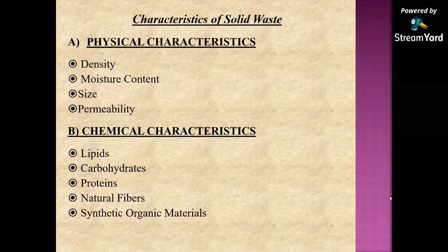Some changes in the density occur as waste moves from sources to the disposal site as a result of handling, wetting, scavenging and drying by the weather, and vibration during transport. Density is critical in the design of sanitary landfill as well as for storage, collection and transport of the waste.